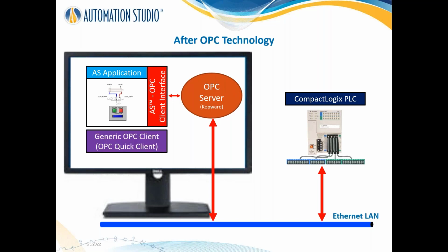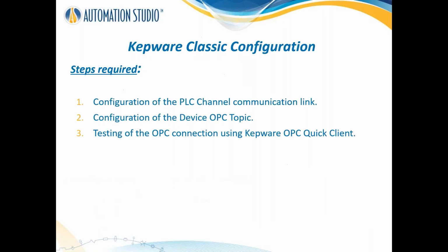Okay, so now in this architecture, as tools, you can use any generic OPC client, of which there are all sorts of applications you can find on the internet, or even given by the OPC server manufacturer. If you use the same syntax that you use in this client interface, it will help debug and troubleshoot to make sure that the settings you do in the OPC server are proper to be able to communicate with its PLC. We're going to look at all these aspects now in this presentation.